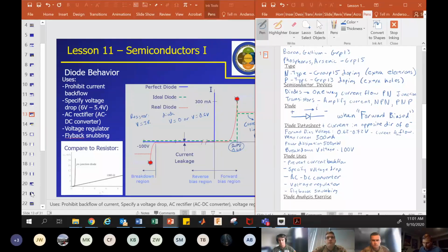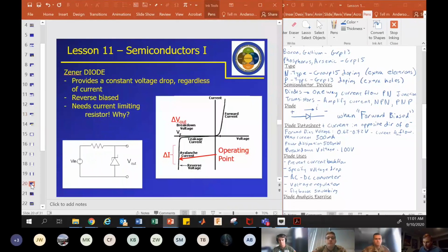A couple of other different types of diodes. The first is called a Zener diode, and it looks like this. So look at the schematic on the lower left. It's got that weird Z-shaped line on the top of the triangle. And this is designed to actually be used in a reverse mode. You can see in this diagram that the diode is pointing in the wrong way.